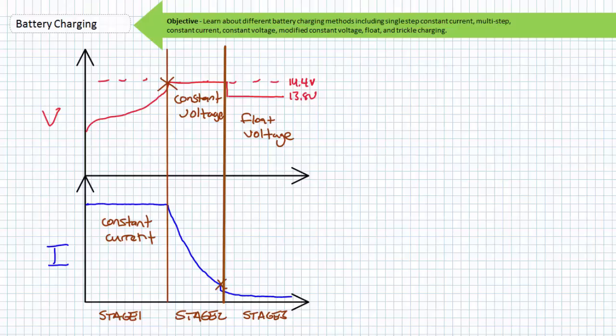Finally, once current has decayed to this predetermined minimum, the charger switches to a third stage, also characterized by a constant voltage. However, this time, the voltage is reduced to the float level sufficient to finish and maintain the battery charge. This combination of a constant current and 2 constant voltage stages ensures the battery is charged to capacity relatively quickly during the bulk stage and receives the saturation charge during the absorption and finishing stages necessary to ensure the long life of a lead-acid battery.